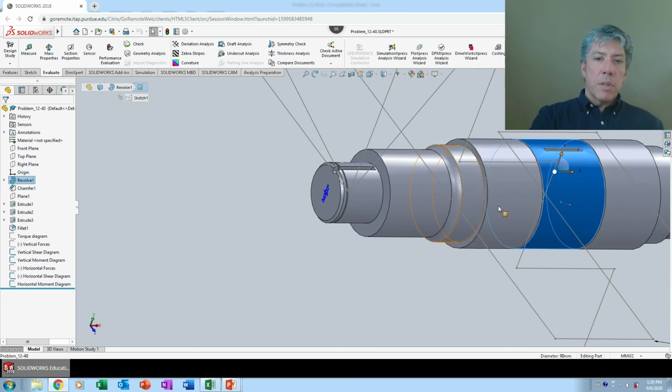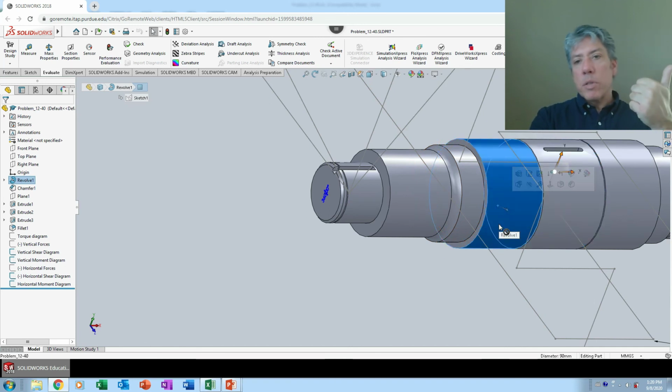So the reason I chose a 69 millimeter diameter here is, number one, save machining time. I could have said 69.5 millimeters if I really wanted to, but why not take off a full millimeter while we're at it? And hopefully machinists would see this unless they're used to it, or maybe I've put a note on the print that this surface could be a fairly rough surface. I'm just trying to get material off of it to make it easy to assemble the center gear.